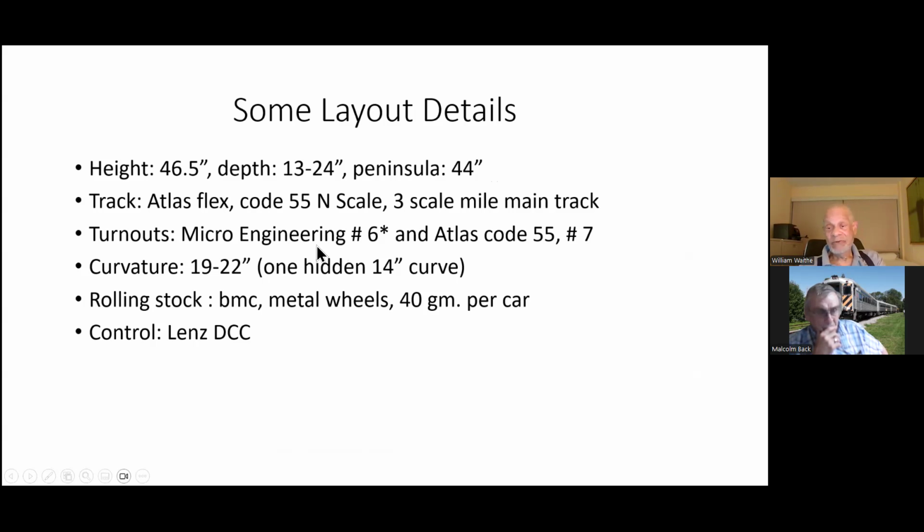Again, I had too many tracks there. And mostly these turnouts turned out to be not in gauge. It turns out that the mold they were using was old and the stock rails were coming out too thick. So we installed them and we were having a lot of derailing.